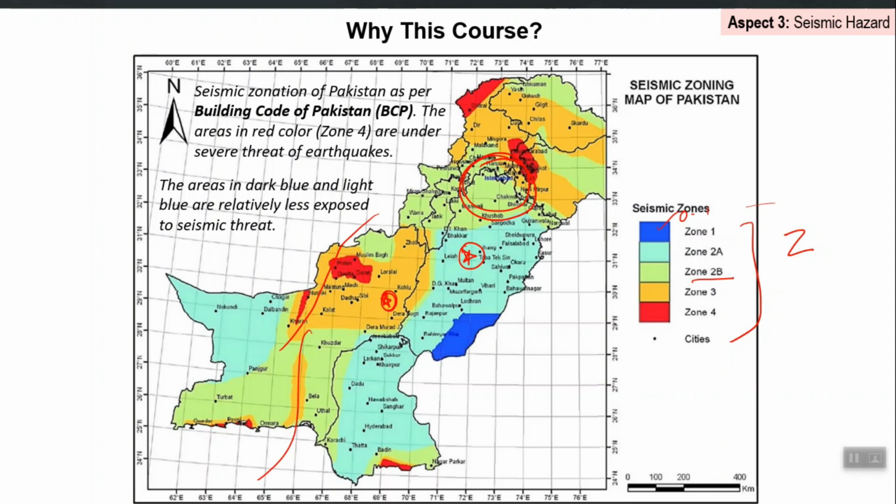Similarly, there is another study which is one of the prerequisites of performance based design, and that is wind tunnel testing. In those areas where wind loading can govern the design of the building, there is a separate study called wind tunnel testing, in which you get a clear idea about the actual wind loading which should be applied to your computer model. There is a whole procedure for that. You make a small model of your building, you put sensors on that model, and you put it in a tunnel, and wind is applied to that model.